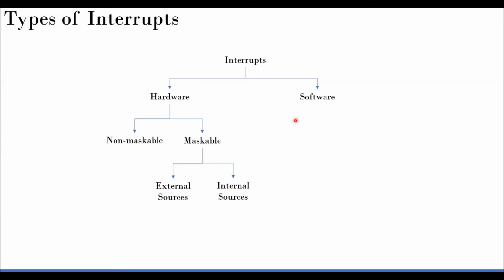So that definitely triggers an interrupt. There is a software interrupt. And what happens during that? It goes to a hard fault routine. There is some interrupt service routine dedicated to that, and typically it is blank. You can fill in something there and it works. And then it comes back to the execution of the program.